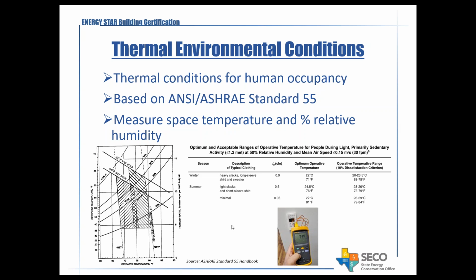Yeah, so this is also one of the important factors to keep in mind. Typically you will have anywhere from 72 to 76 or 78 degree temperatures in the spaces. It needs to be within those limits. Relative humidity needs to meet the ASHRAE requirement, so it'll be 50 to 60%. So we'll be spot checking.